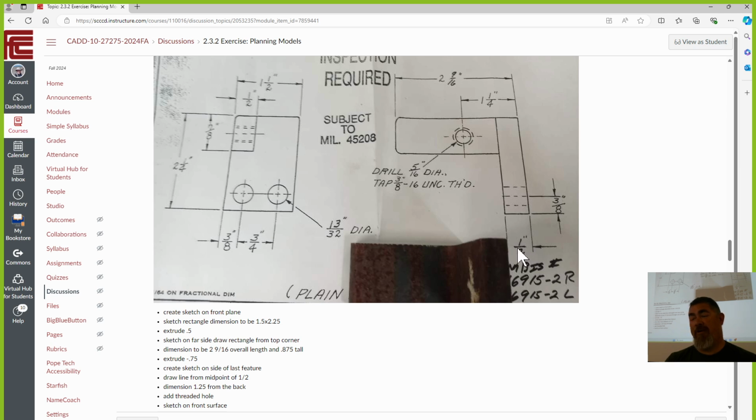But if you just type in the numbers and I decide I want to change this thickness, but keep that overall the same, now you have to go back and edit your math. Or you have to make a parameter, and then it's okay, because it's that minus whatever this number is, minus D, or back thickness, or whatever you call it as a parameter. Then sure, it works as long as I can change this one without affecting that one. But if I change this and it affects that, or I have to go back and manually edit it, then it's not a good thing. Okay.